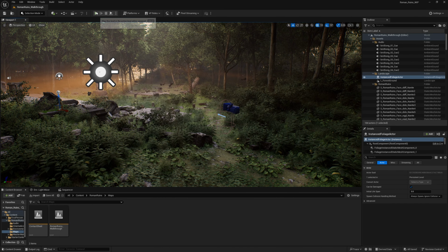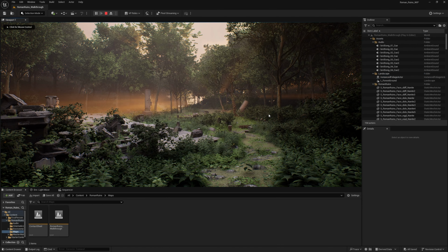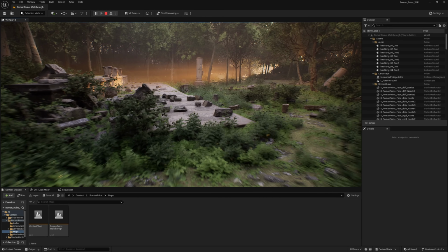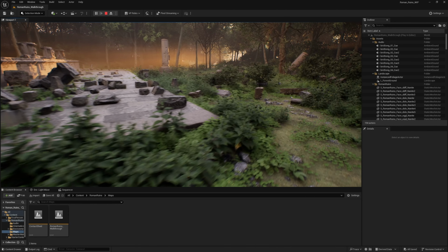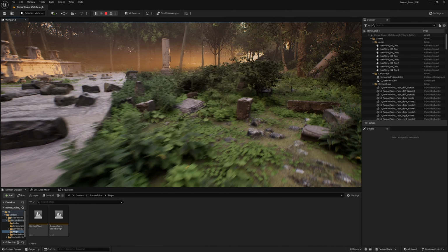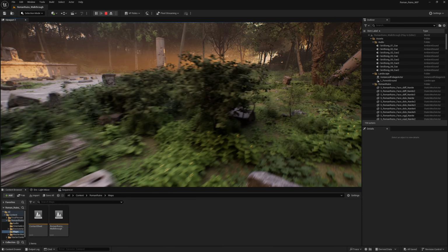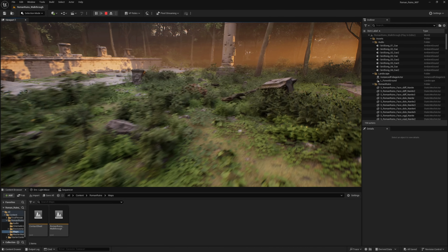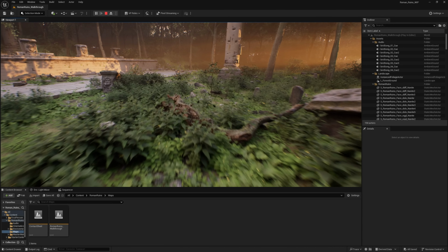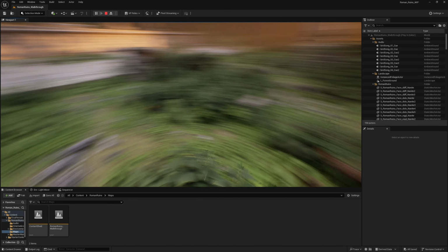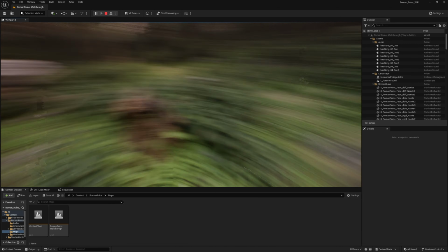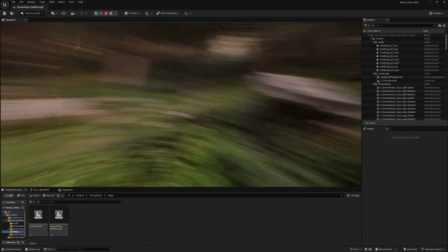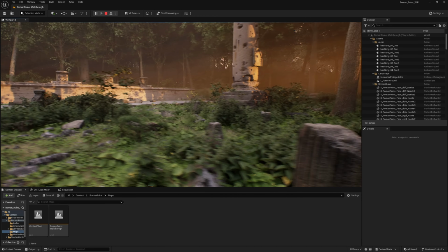But here's the trick: once I hit play, most of it is going to disappear. There's going to be a slight boiling effect still, but 80-90% is going to disappear immediately. So the fix is either I put in this command here in the console to reduce it to this level, and you're happy with that, or you have to do the lighting for the foliage in the old school way, where you don't use Lumen for the lighting. Alternatively, you can scale down the amount of vegetation you have, and it will look a lot more stable then. But that's where we are at the moment with this.